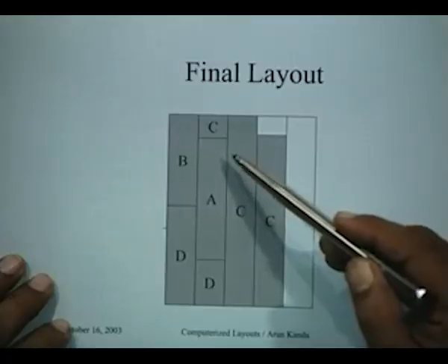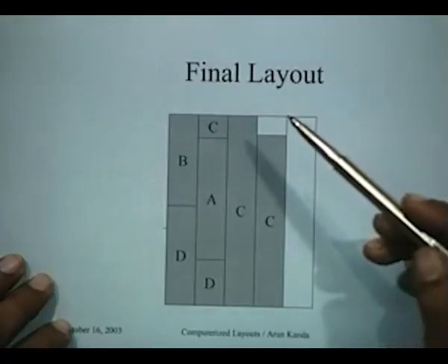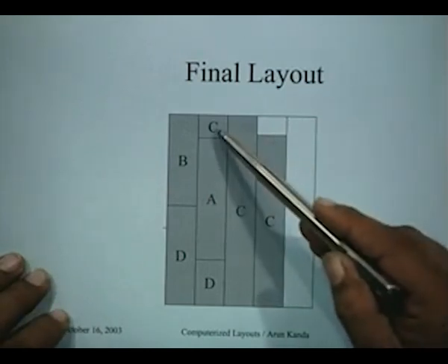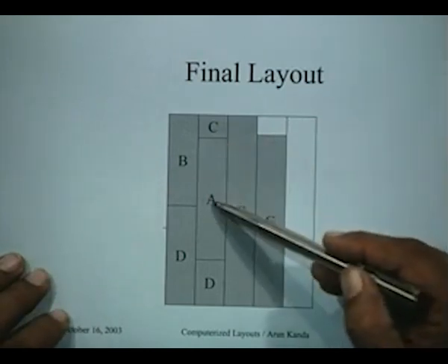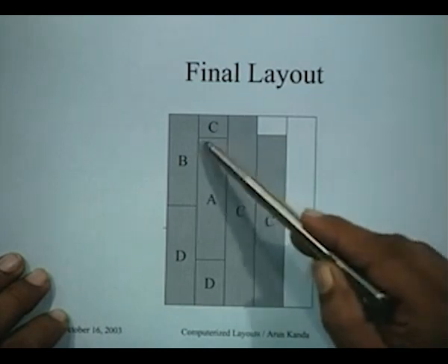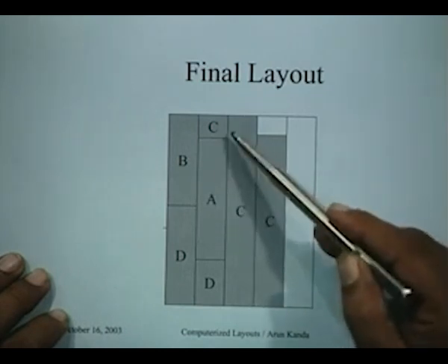What happens if the department C has X rating with all the other 3 departments? Will it be placed very far away? No, what would happen is that all departments which have an X rating are generally placed randomly in this case. So they could be coming anywhere. But in this particular case, the placement of C is governed by its relationship with A, which is where you cut off the tape last and then place it.